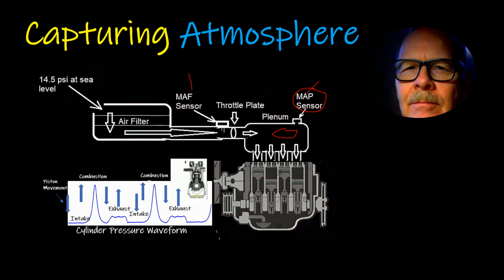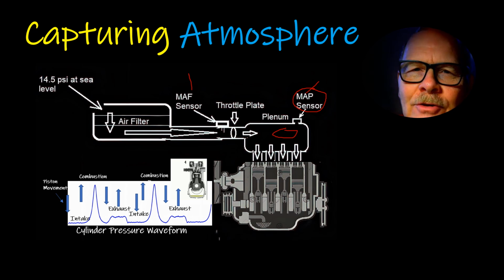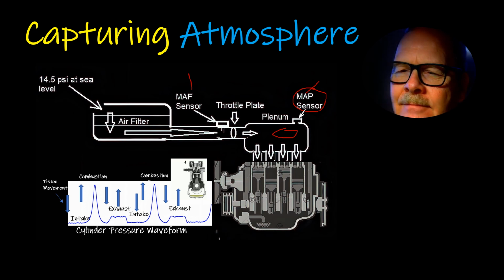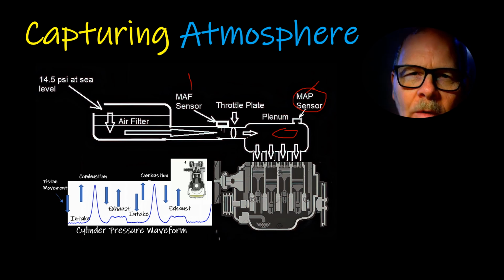General Motors had a booger of a time with that in the mid-'80s, and they had those mass airflow sensors, and the engine wouldn't be running right, and you'd whack the mass airflow sensor and it would make the engine change the way it sounded. They eventually went back and had MAP sensors put back on those things, as a sort of a backup to the mass airflow sensor. The MAP sensor is also good at telling you if you have EGR flow and that kind of thing.